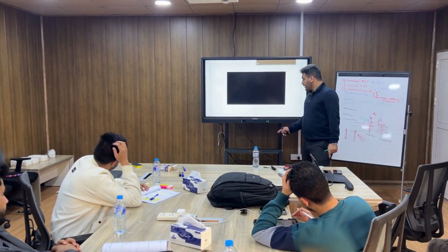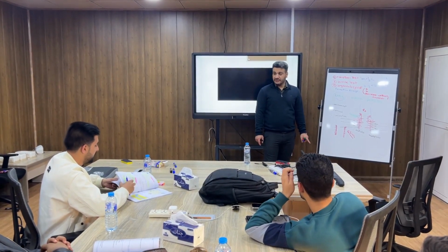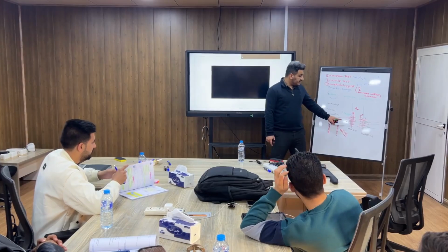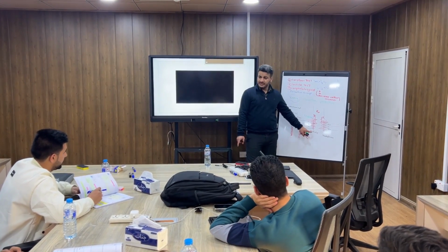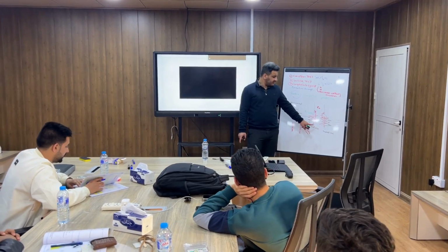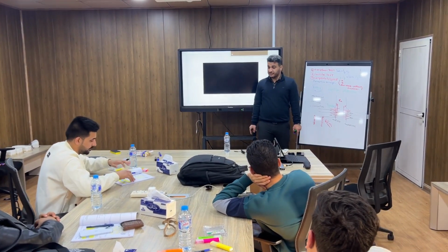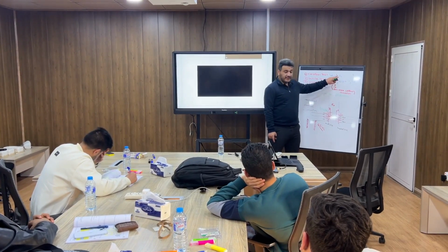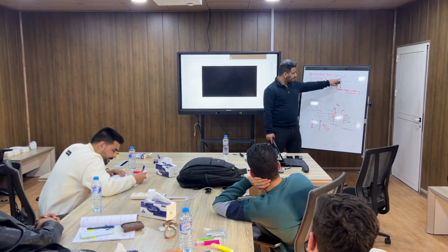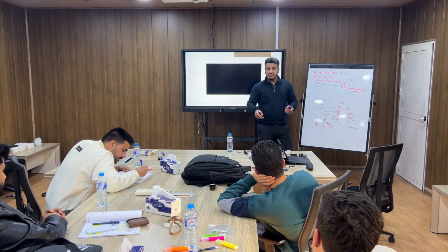So right now we have reviewed the water cut control if we have a high amount of water cut. But the problem is related to formation damage. I think we should review the formation damage related to fine migration in the reservoir. Solid particles more than 1/3 of the average pore diameter collect as a mud cake and are easily removed by the flow back.